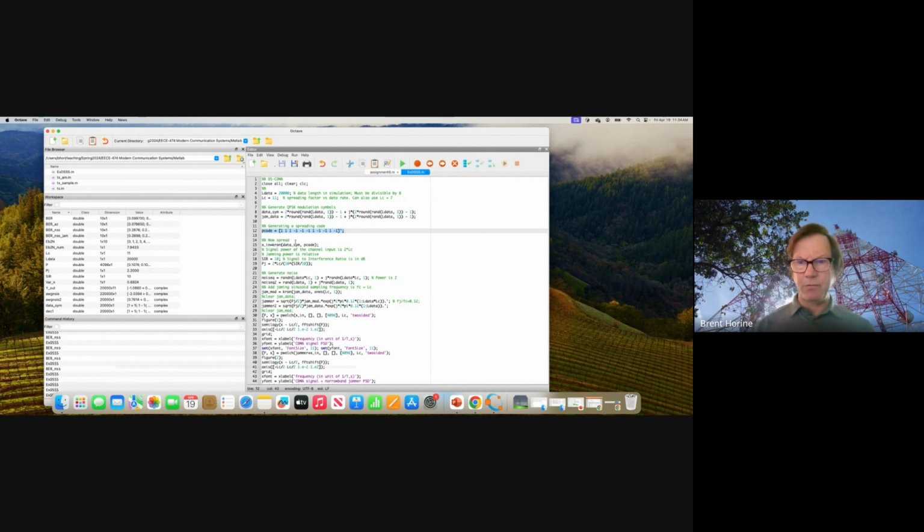In CDMA, we have a whole family called Gold codes in the 3G type standards, which are a little bit archaic at this point, but CDMA is still used in one form or another in a lot of systems. In this case, they use an 11 chip Barker code, and Barker codes are a family of codes that have these good autocorrelation and cross correlation parameters.